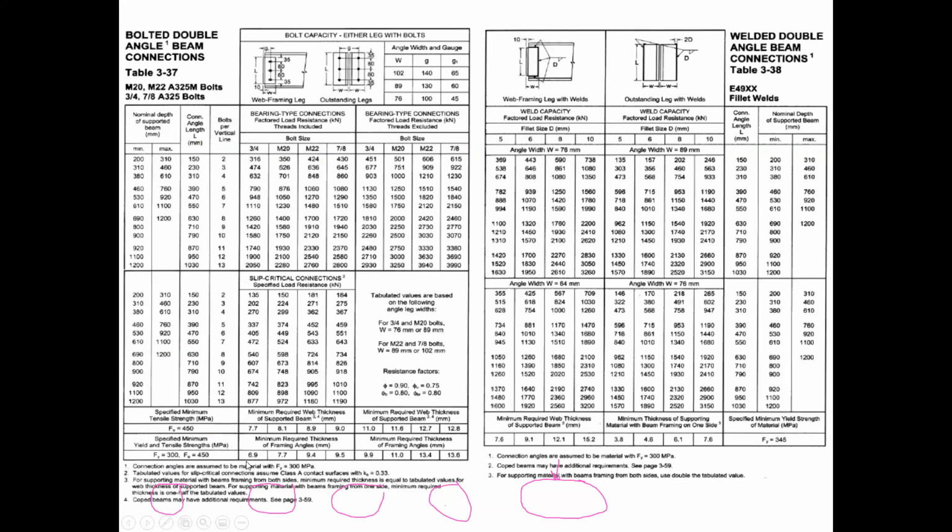Okay, so all these values here at the bottom of the table are just to assure you that whatever VR values you take from the tables are adequate. In other words, this thickness will guarantee me all these VR values. Now, if I happen to have something smaller than 3.8, say 3.2, then I can take 3.2 divided by 3.8, take the values in the table and reduce them, and see if I still have enough.